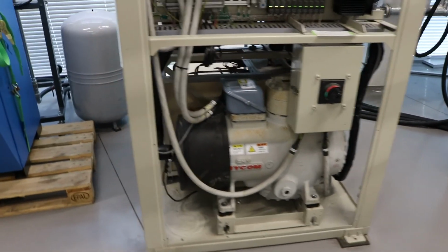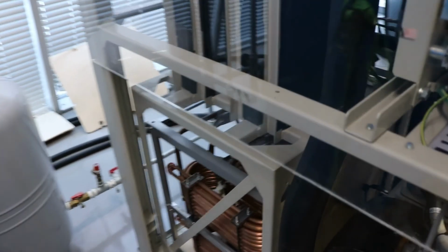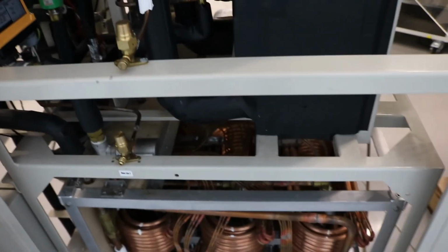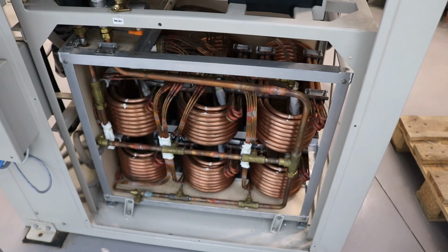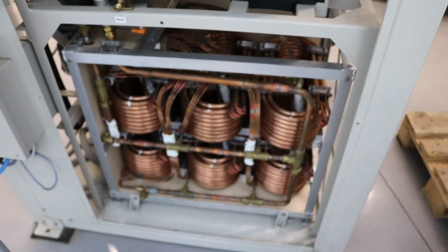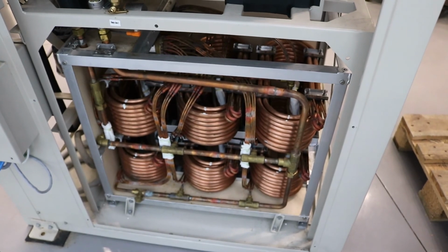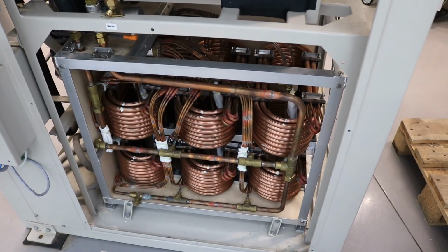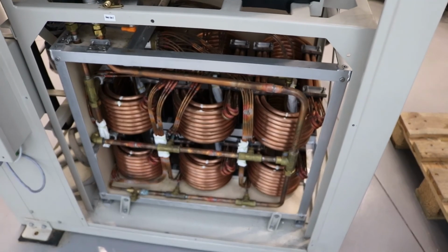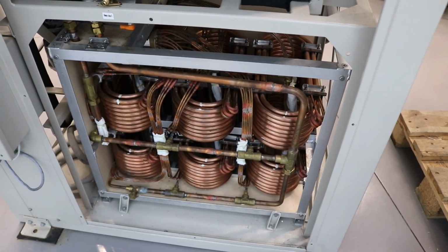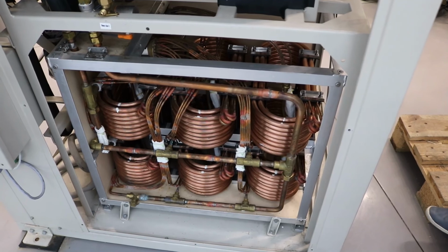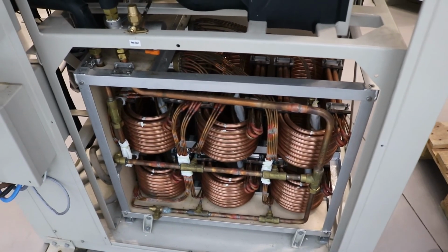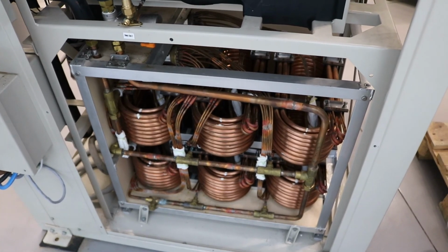Next, we don't have a condenser because the CO2 in the cycle is compressed to such temperatures and pressures that it goes into a transcritical state. In the transcritical state, we don't condense the CO2, we just cool it, and we do it in a gas cooler. This is a gas cooler, and it's in the place where a normal heat pump has a condenser. It cools the transcritical CO2 so that it goes into liquid.